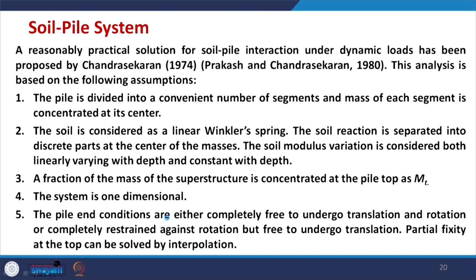So, what has been done? In the solution which we are going to consider, two conditions are considered. In one condition the pile top is completely free, that means it may undergo rotation as well as translation. In the second case, the pile top is restrained against rotation, but still it may undergo translation. That means in both cases we are allowing translation, but in the first case rotation is free, and in the second case rotation is restrained. So we will discuss both cases: pile top free and pile top restrained against rotation.